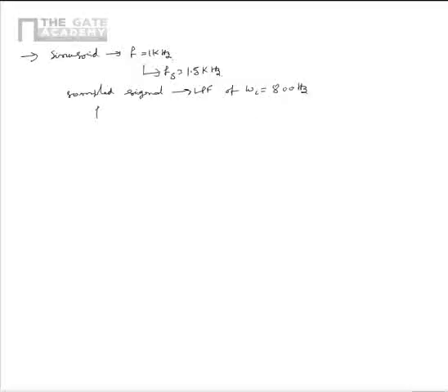We need to find the frequency of the output signal. As per the given problem, there is a sinusoid at a frequency of 1 kHz. The same is sampled at 1.5 kHz. Now, the sampled signal is passed through a low pass filter of cutoff frequency 800 Hz. We need to find the frequency of the output sinusoid.